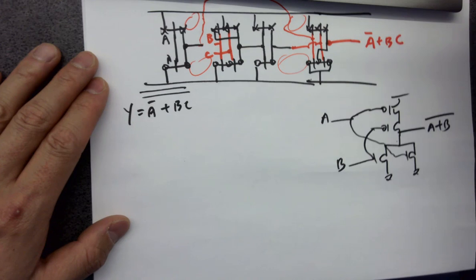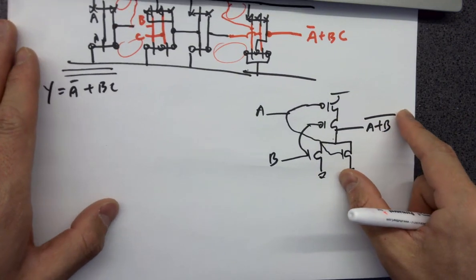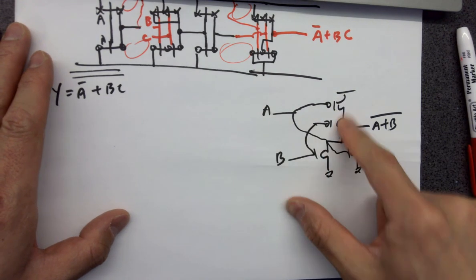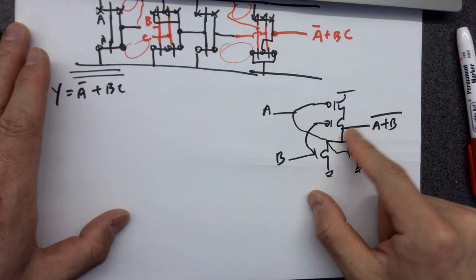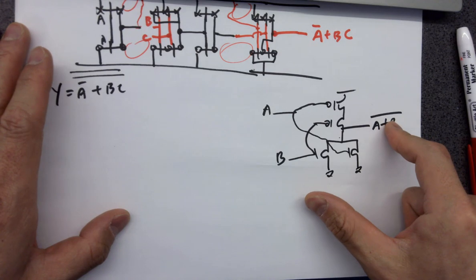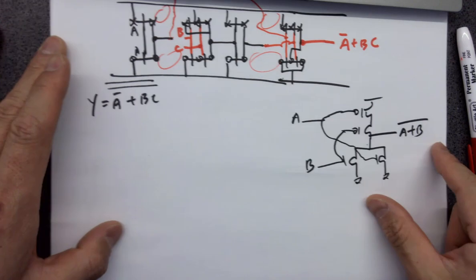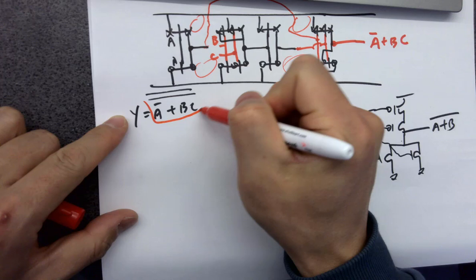And because we know that every time we draw AOI logic, there will be a bar on the top. The reason for that is when the input is 0, it opens up the PMOS and shorts this one to the VDD. In that case, 0 will give it 1. That's why it's always getting inverted, right? So that's why it's called AOI. It's AND, OR, and invert. It's AOI, okay? And that is why we want to keep a bar with it.